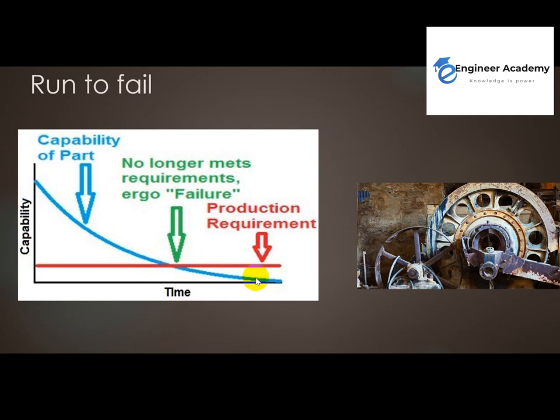We have two types of failure actually: function failure and performance failure. Function failure means the equipment is not capable to give this function anymore. And performance failure means the function is not performing as expected anymore. As an example, the filter is a performance failure. Yeah, it's still working, but it's not performing as expected. If it keeps running like this, it will make a big problem or a catastrophic failure. So you need to take action to replace it.